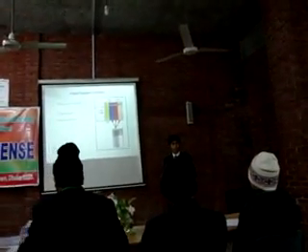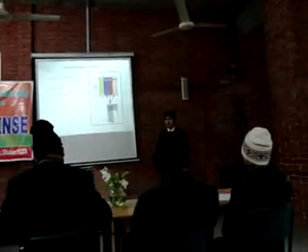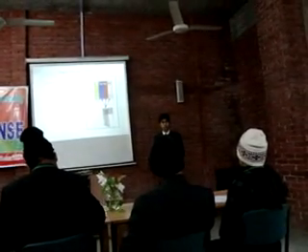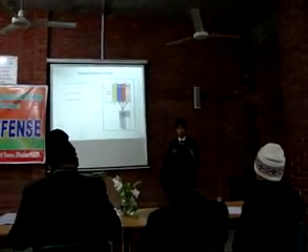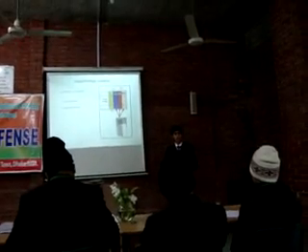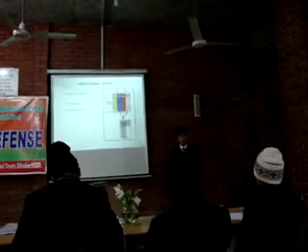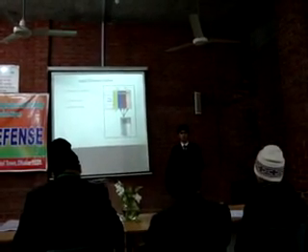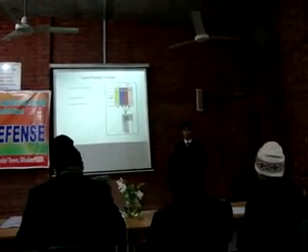And which language did you use? I use the TSX Micro 3720 PLC. This PLC uses the software PL7, and this PL7 provides 3 types of programming languages: instruction-based language, ladder language, and FBT, that is flowchart-based language.